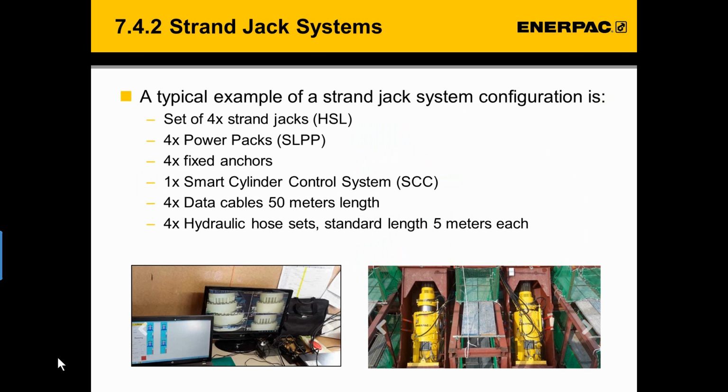Strand jack systems are, as a general rule, supplied in sets consisting of one set of 4 strand jacks, 4 power packs, 4 fixed anchors, 1 smart cylinder control system, 4 data cables, and 4 hydraulic hose sets.